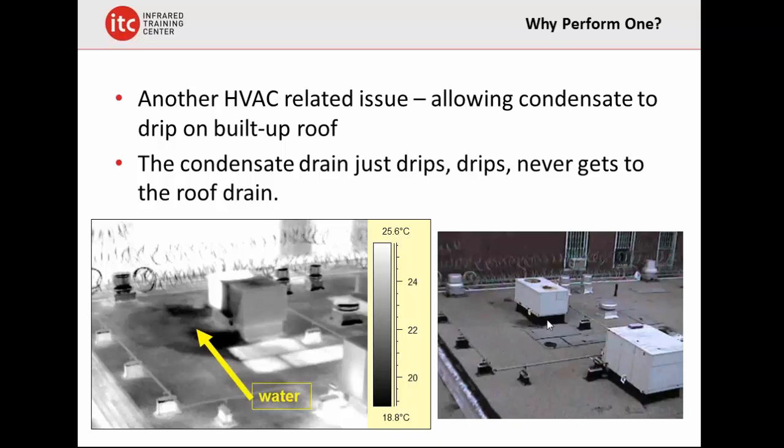Now, they could have saved the roof just by taking the condensate drain over here and pitching it off the side of the roof. There was another drain behind here, but they never did that. It failed the entire roof, to the point where when I walked through the control room where they're controlling the movement of all the prisoners, they had sheets of plastic going down into 55-gallon plastic barrels, and they had sump pumps in the barrels to pump the water out.